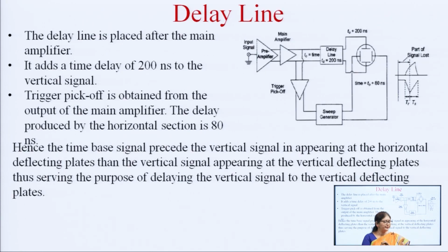Now, when we apply the input signal at the vertical deflection system, the signal is passed through the vertical amplifier, and then the signal is directly fed to the vertical deflection plates. But in the horizontal direction we can see that the signal is passed through the sync circuit.